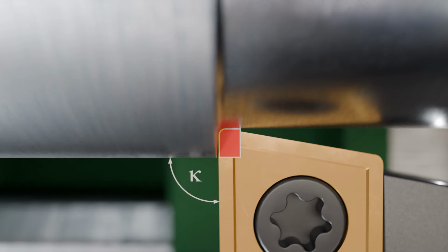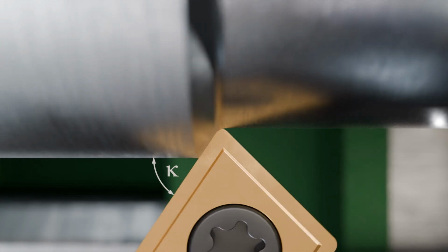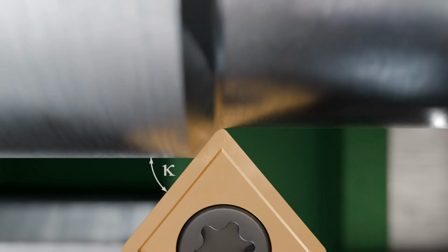Approach angles of 90 degrees or more are required when producing right-angled shoulders. Angles greater than 90 degrees have the advantage of slightly increasing the effective cutting edge length engaged in the cut. However, this inevitably reduces the nose angle epsilon, which in turn leads to a less stable cutting edge. As already mentioned, the approach angle not only influences chip removal but also affects the forces acting on the turning